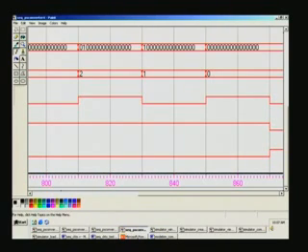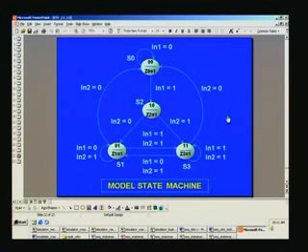the state machine. We are looking at the waveforms for the state machine, and in this we have 4 states S0 through S3, and there are 2 inputs, based on which a transition is made from one state to another. For example, if it is in 0, it remains at the same state, and for each of these states Z0 through Z3 are mere lamp indicators, and the actual state is 0 0 1 0 and so on. So looking at the waveform for this, we have here